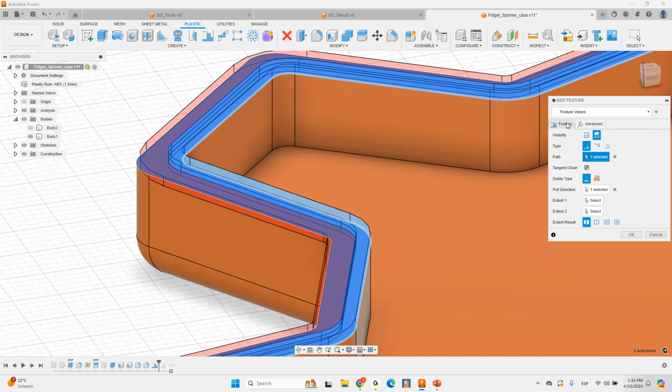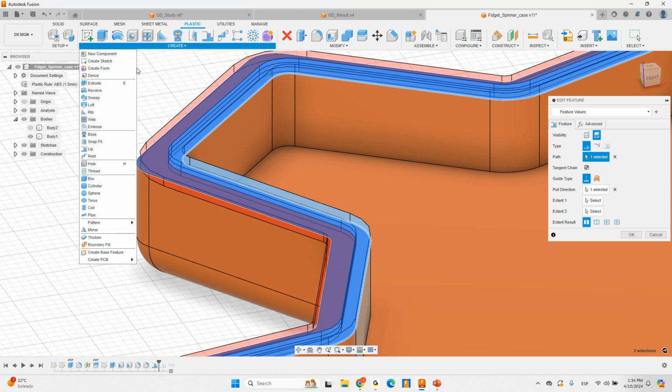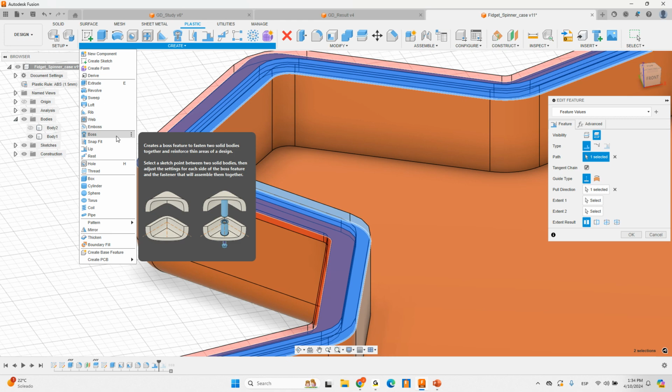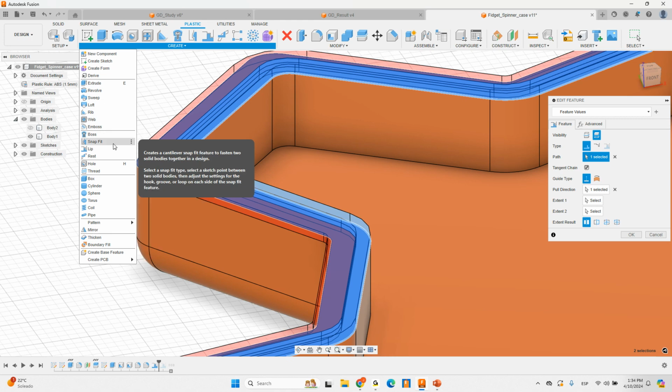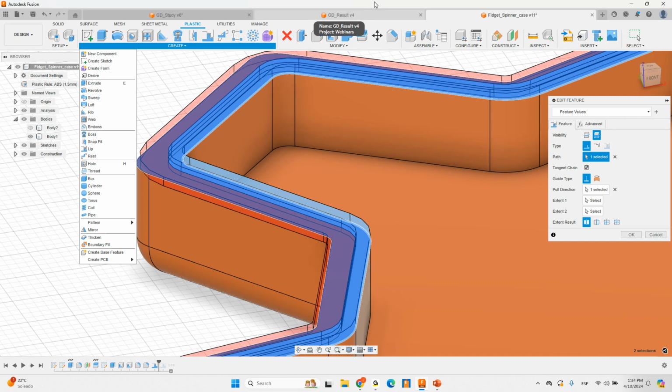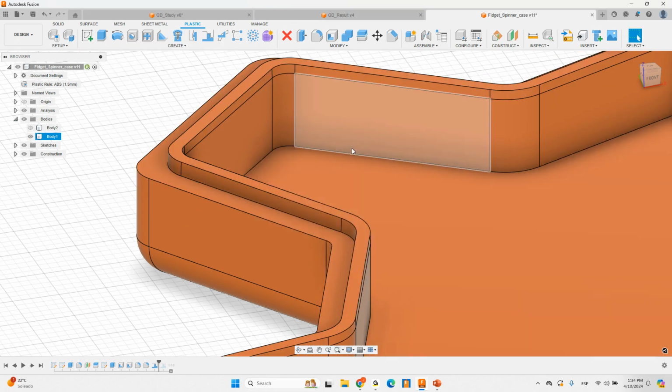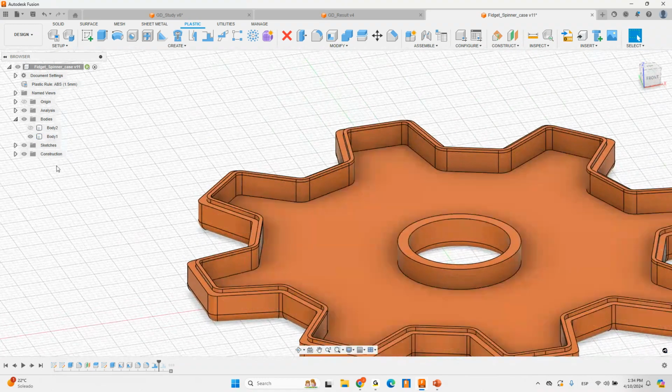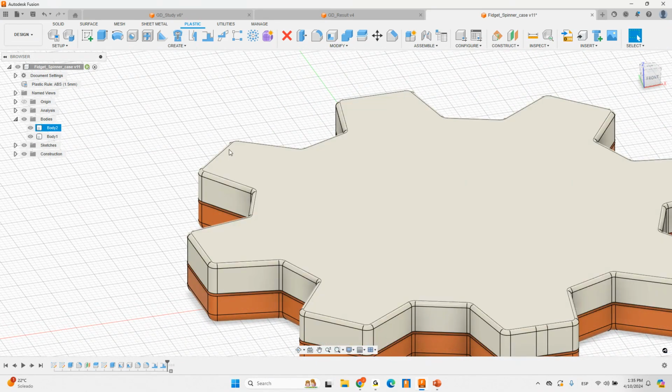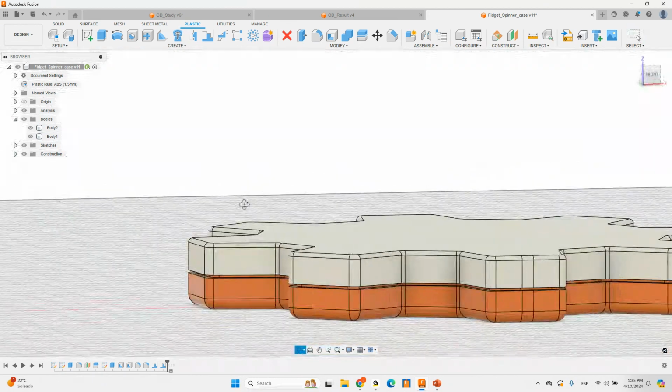There's no need to do complex operations, complex sketching, creating a bunch of extrusions, all of that. We can take advantage of very useful tools like boss, snap fits, using lips, or creating geometric patterns, polymetric lattices, all of that with our design tools, right? So I got one lip here and a lip there for the lid, body lid.